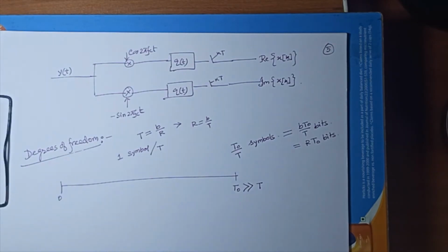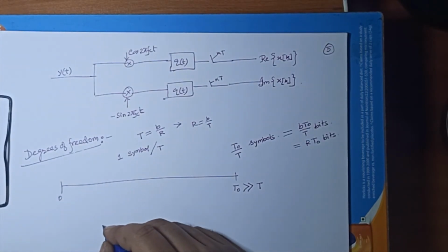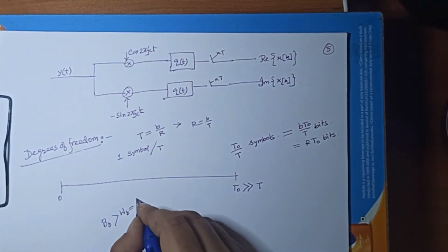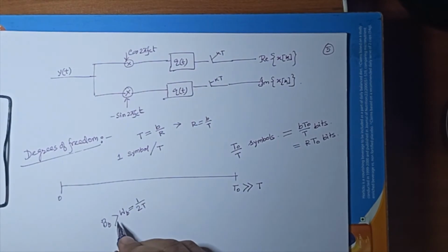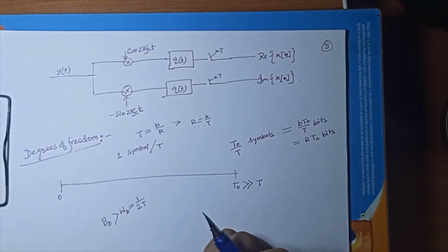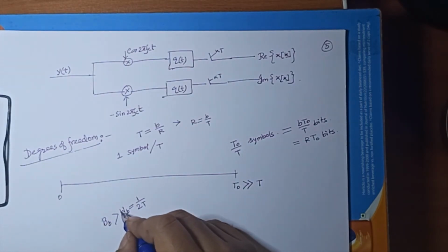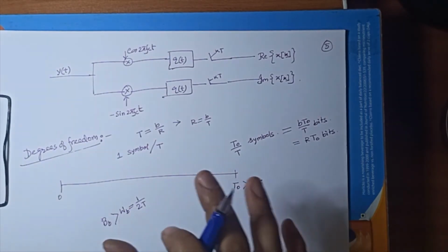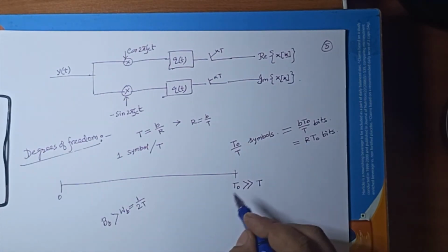Now let us look at this from the degrees of freedom of the baseband waveform point of view. So we know that the baseband waveform, what is the actual bandwidth? The actual bandwidth is a little greater than WB, which is the nominal bandwidth. Little greater than. So it is basically parameterized with respect to that alpha, right? When we designed the raised cosine filter. But we can take it arbitrarily close to this WB.